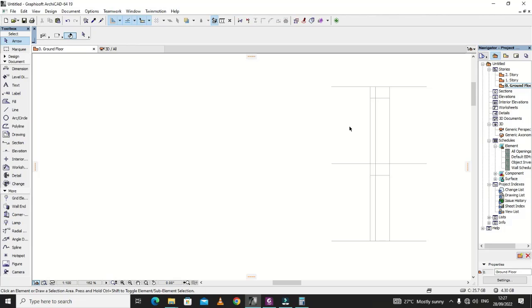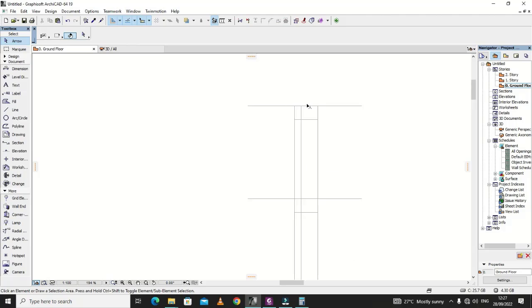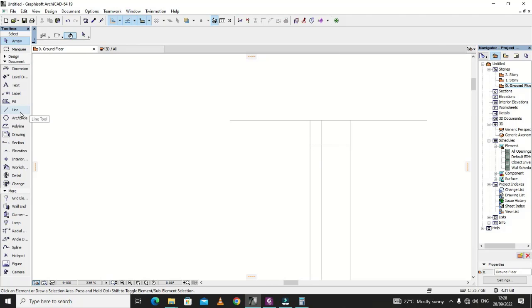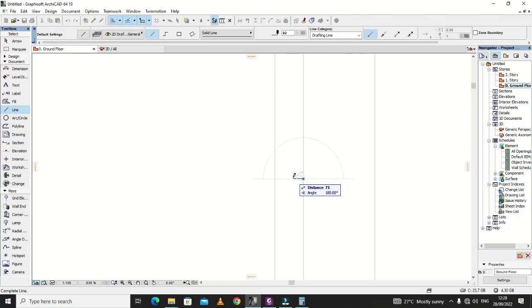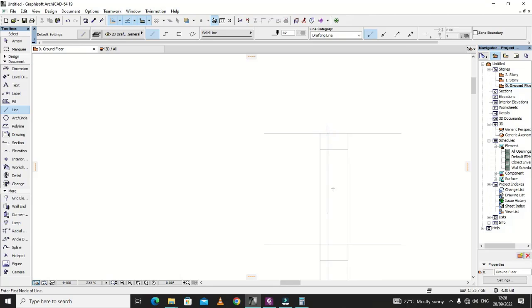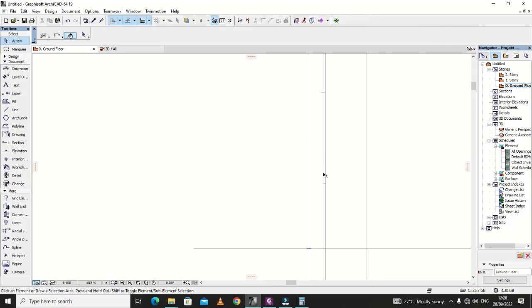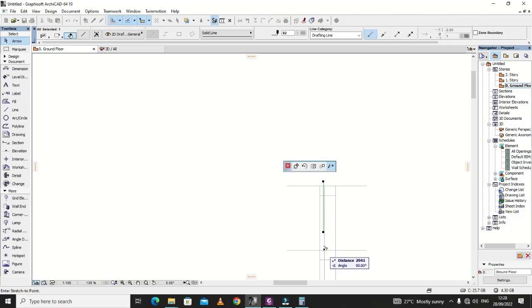Now that we have already shown the beams, the next thing you're going to do is to draw the bars. For the bars, the first thing you have to know is the cover. For me, I'm going to use 30 millimeters. So let this line just extend beyond that way. And then on this side, this line should go only up to where the kicker should be.